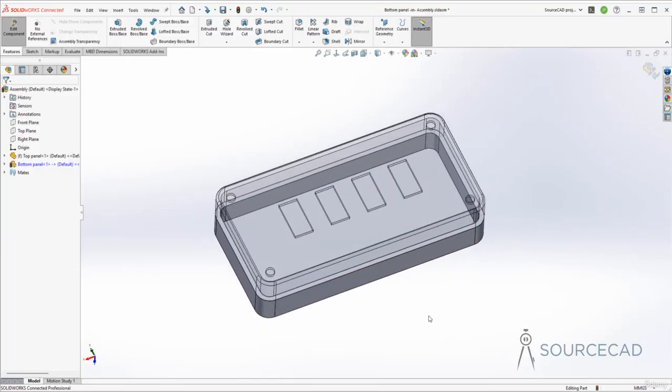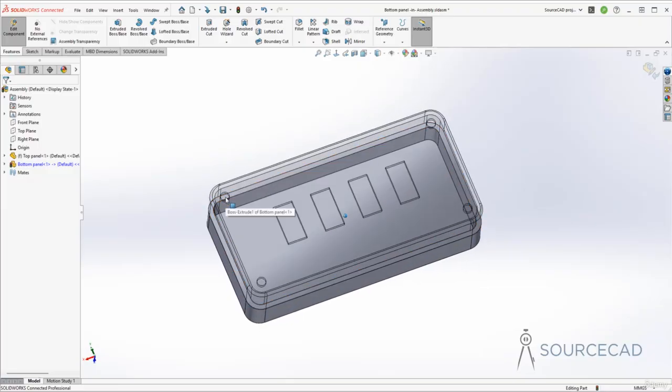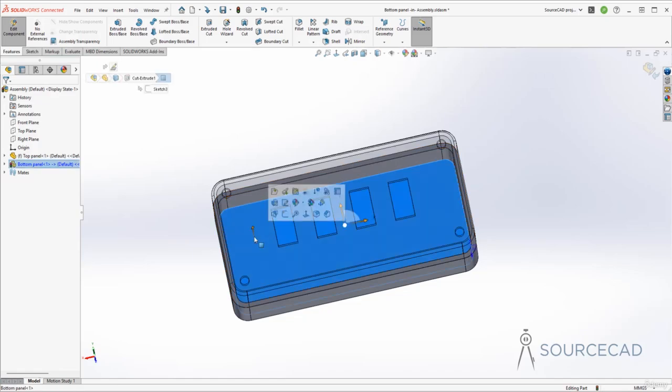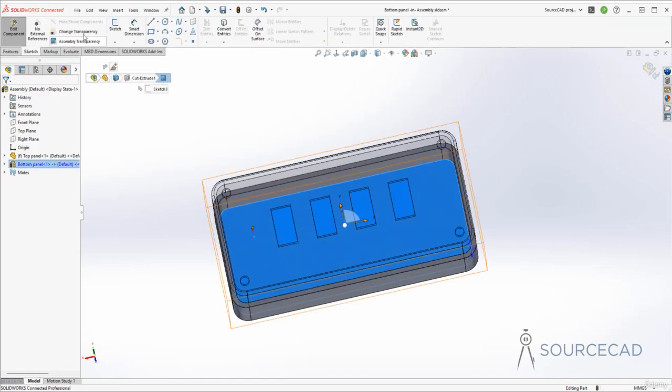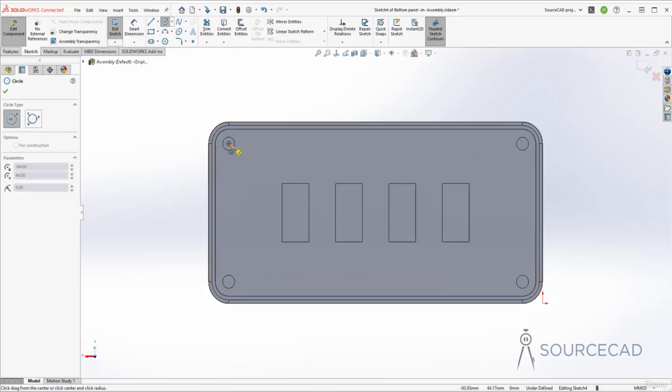Now, another thing that we need to do here is, well, add these holes. So these holes are for a screw and we want the cylindrical grooves right here for these screws. So for that, I'll just select this bottom plane and sketch and go to sketch. Now, once again, I'm going to use these holes as reference for making this feature. So I'll go to circle and right at the center, I'll just make the first circle and the second and the third one and the fourth one.